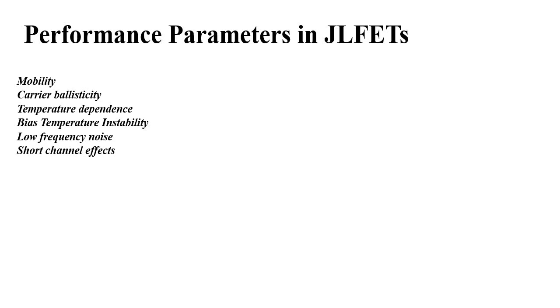Short channel effects are basically the effects when we are scaling down the channel length, we face some kind of difficulties in terms of drain induced barrier lowering, in terms of threshold voltage roll off, in terms of gate induced drain leakage, in terms of leakage currents. So all these are the performance parameters that we have to keep in mind while designing the junctionless FETs.